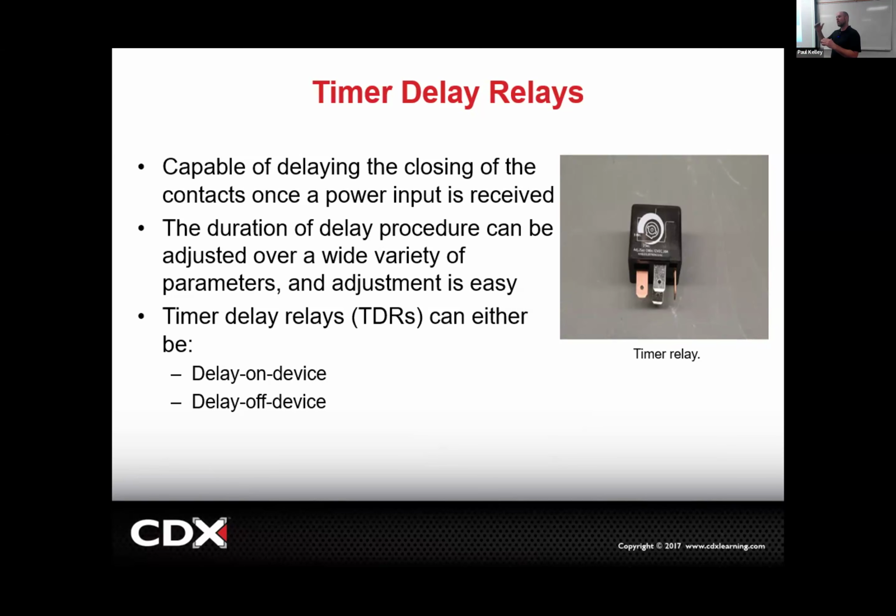It'd actually be better to keep the car running for like 3 minutes or 5 minutes or 15 minutes, depending on how hard your drive was, and just idle, because the hot oil that's in the turbo is going to circulate down in the engine, and then the engine's going to somewhat cool it with an oil cooler and then send cooler oil to the turbo, which will help cool the bearings down and just gradually let everything cool down. Well, the thing is, you want to get out of the car, right? You got home, you want to go inside.